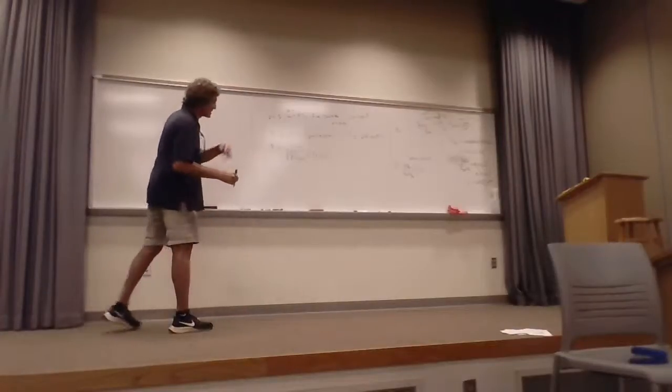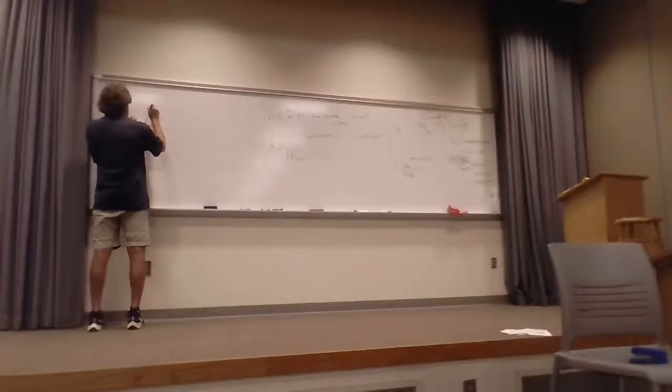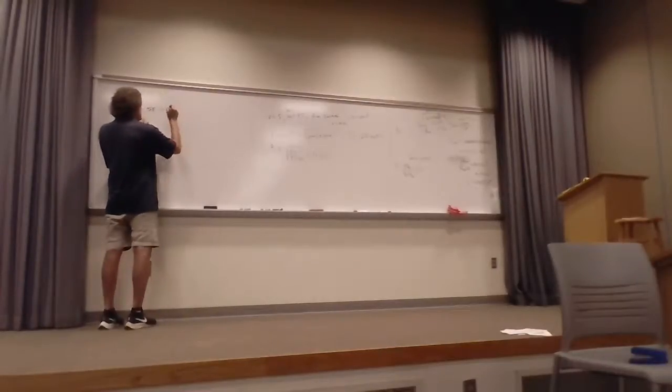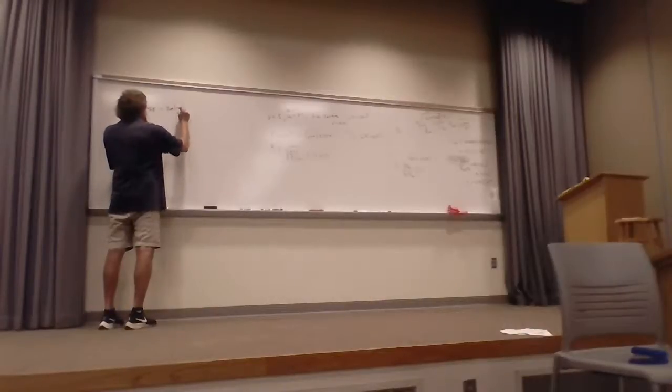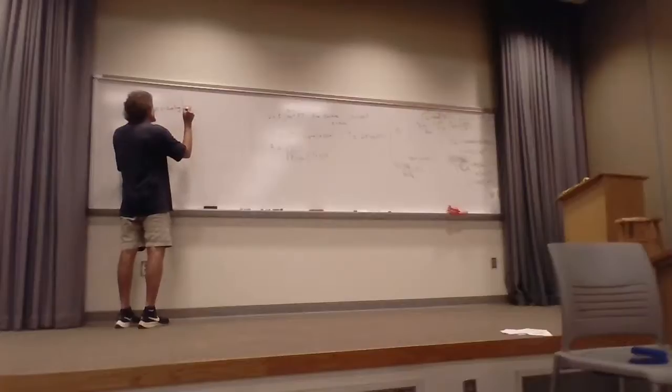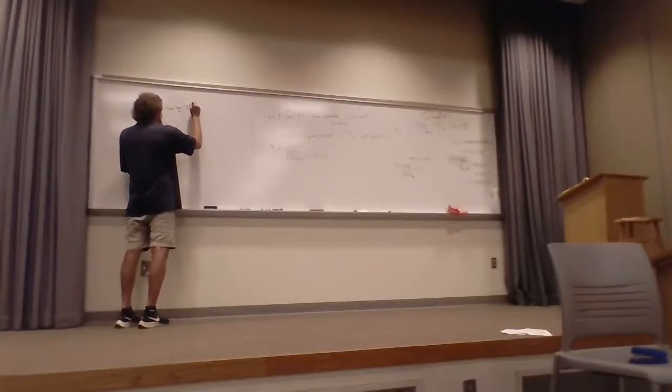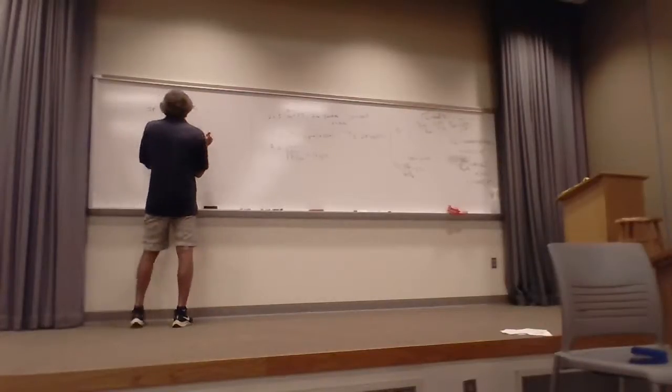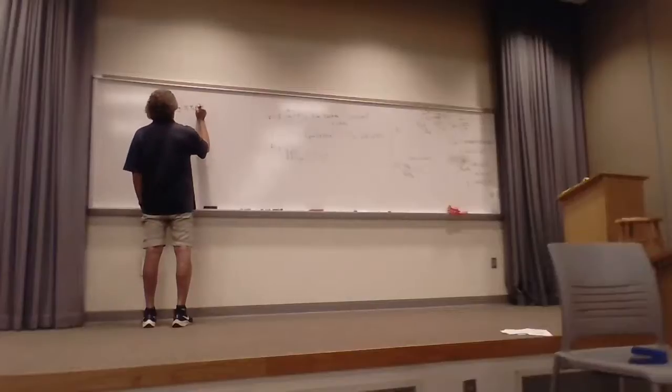Now what I'm going to do is take the definition of shielding effectiveness. Remember, this is with voltage, not power, which is 20 times the log, base 10, of the magnitude of tau 1, and actually it's minus this, tau 1 times tau 2, times e to the minus alpha z.